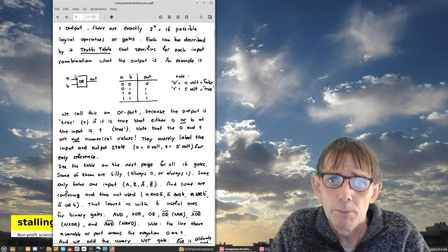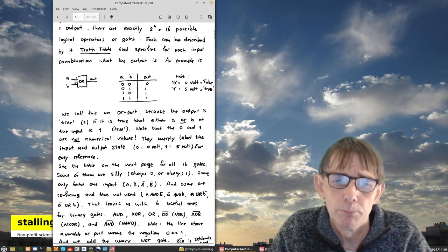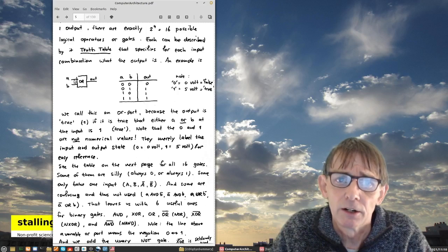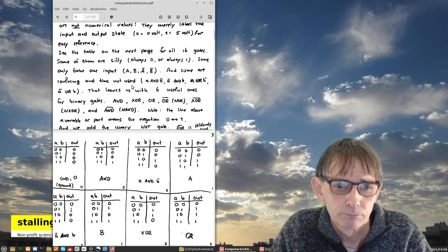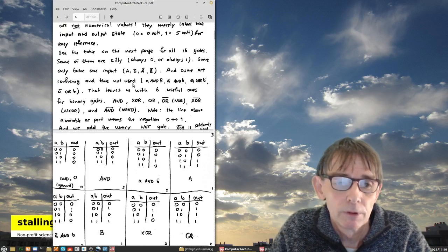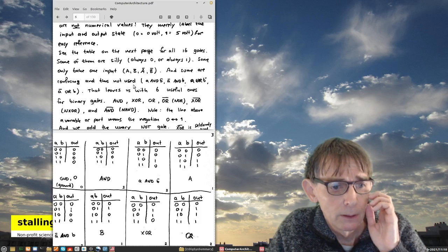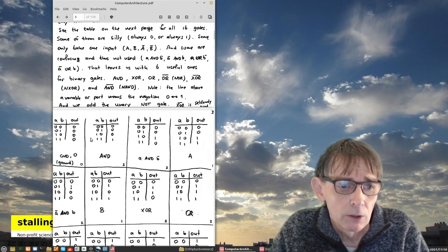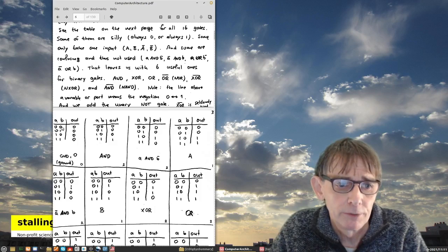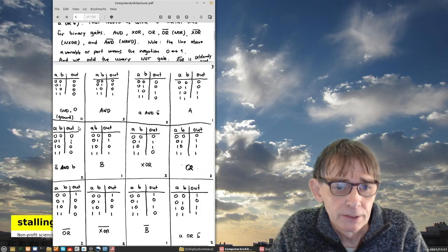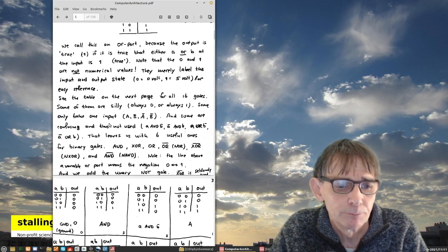And if you now have two inputs that can each be binary, and one output that is a function of these two inputs, then I can imagine that there are 16 different such logic operations. Two inputs, each with two possibilities, so you have 2 to the power 2 input combinations, and each of them describes one output combination. In this case you can have 16 possible logic gates.